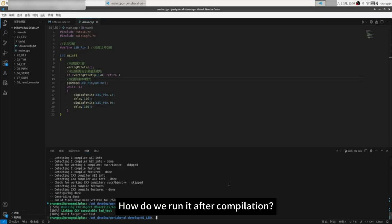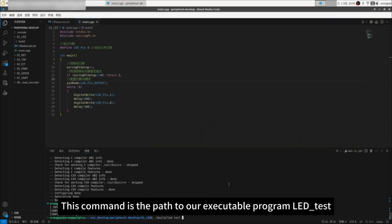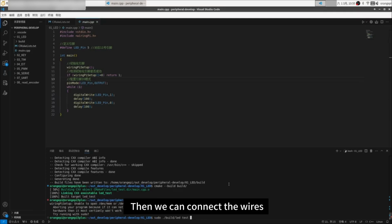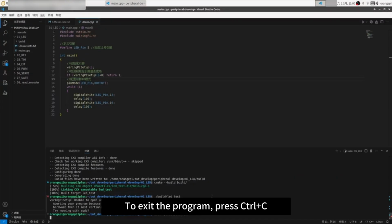How do we run it after compilation? We need to enter this command sequence in the terminal. This command is the path to our executable program LED_test. Remember to prefix it with sudo. Notice here I forgot it, causing an error. Controlling GPIO requires root privileges. Then we can connect the wires and observe the LED lighting effect. As seen, it works without issues. To exit the program, press Ctrl+C.